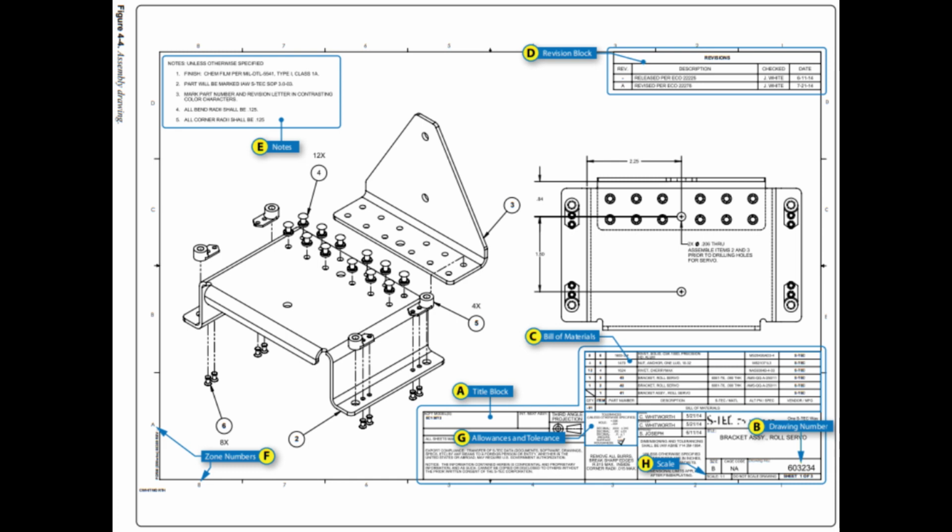Figure 4-4G. For example, using 0.225 plus 0.0025 minus 0.0005, the plus and minus figures indicate the part is acceptable if it is not more than 0.0025 larger than the 0.225 given dimension, or not more than 0.0005 smaller than the 0.225 dimension. Tolerance in this example is 0.0030, 0.0025 max plus 0.0005 min.